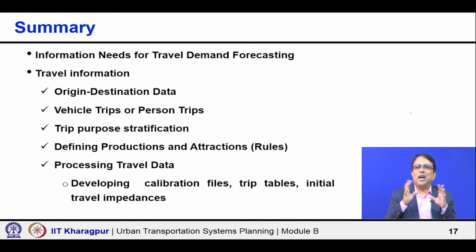So you get some idea of the zone to zone travel time, which you use as a starting point for doing your trip distribution, mode choice, assignment, all this. But finally, once the loading has been done, you can always go back, and based on the actual loading, the actual travel time or travel cost, you may update the whole process, right.